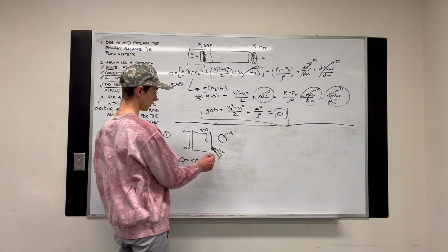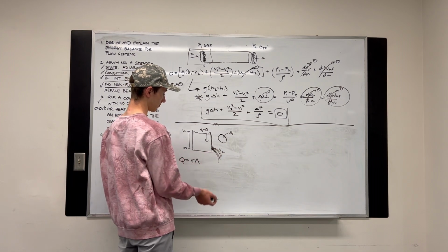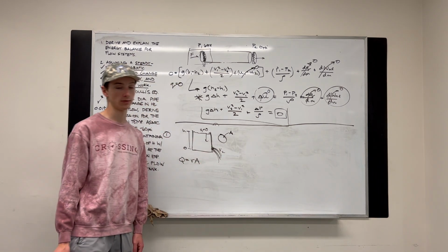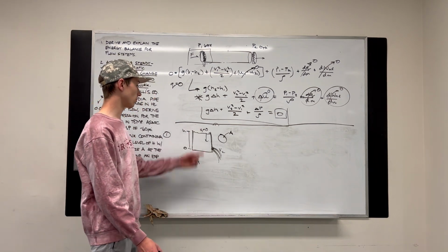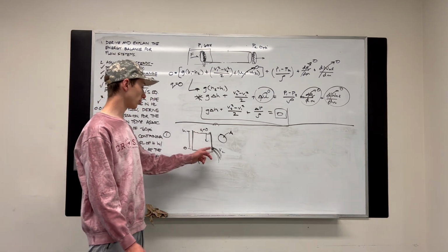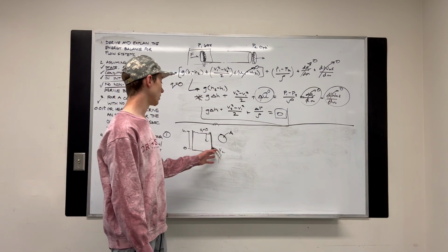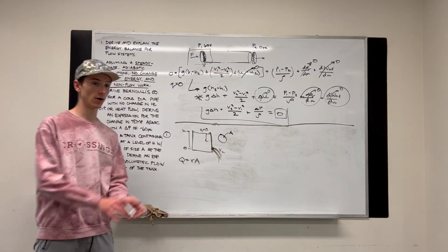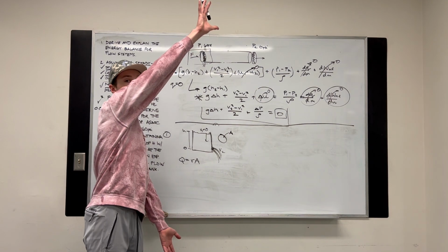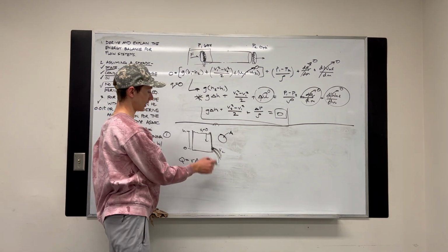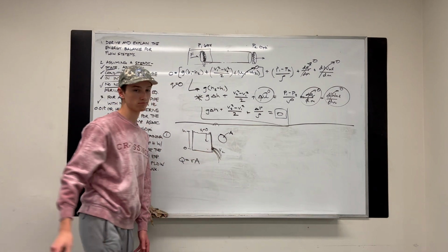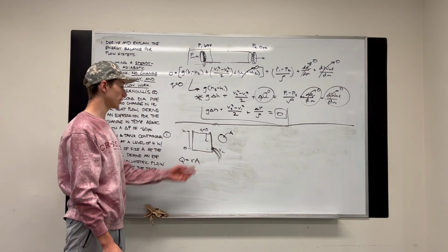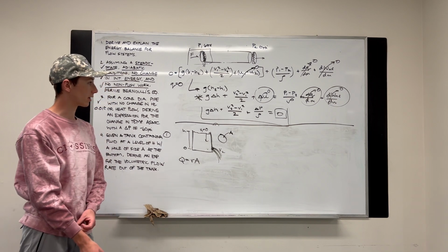Okay, and is there a change in pressure? Well, when it comes out, it's atmospheric pressure. If we're using gauge pressure, we'd say 0, right? And at the surface of the water, the pressure is 0. If the pressure of the water was more than 0 when it came out, the water would just kind of spray out like this, right? But it's kind of just pouring out. So there's pressure behind it, obviously, but when it leaves, it's also 0. So really, there's no pressure component that we have to worry about.